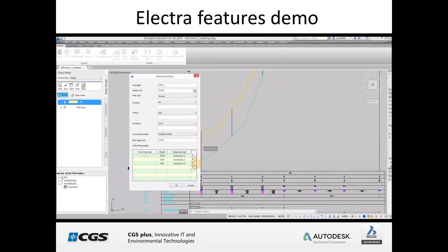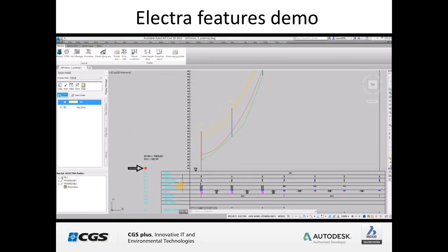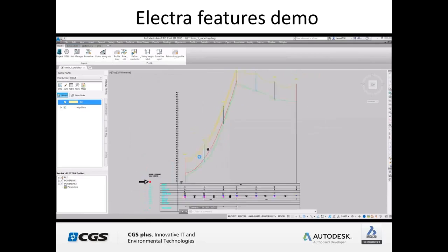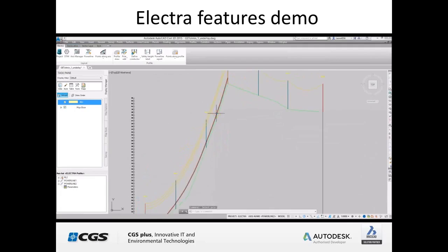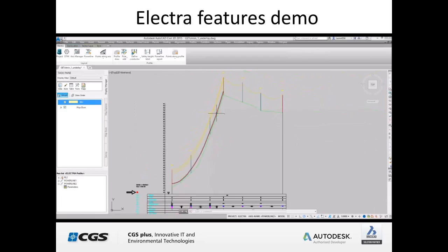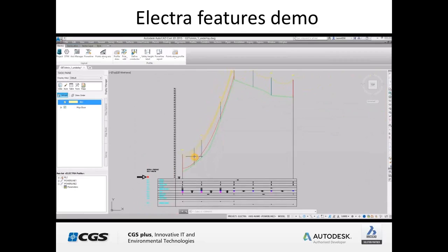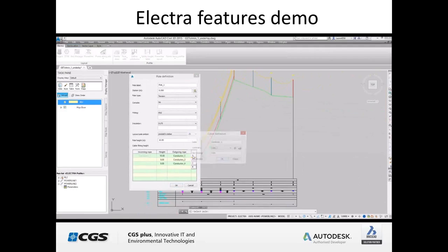Okay, so what we'll do here is make those safety height checks. We can define for this lowest conductor whether it meets the 6 meters safety height toward the terrain, and as we can see here, that is met. But we can also check the safety height between 2 conductors, and we are interested in the one between the uppermost conductor and the middle one, and here we will set 0.9 meters of height.